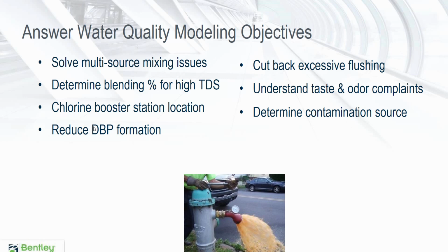You have different sources that you're trying to mix, maybe chloramine and chlorine sources, and you're trying to figure out how much volume of one or the other you should be mixing. Same thing for total dissolved solids. Maybe you've got a well field that has high TDS and you're not quite sure how much TDS concentration of that one well field you should bring into the rest of the collection system.